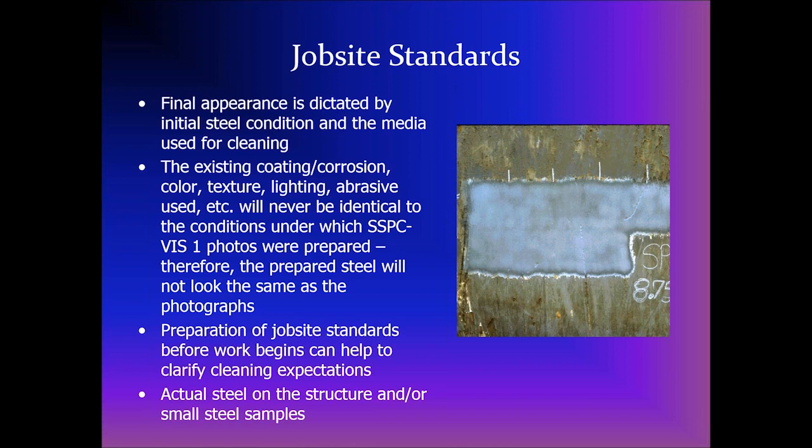So in this case, prepare the job site standards, agree that this is in fact the degree of cleaning specified for the job, and use it to kind of hone in and adjust your eye to recognize the degree of cleaning required. It's a very effective way to eliminate disputes with regard to the degree of surface preparation required and being achieved.